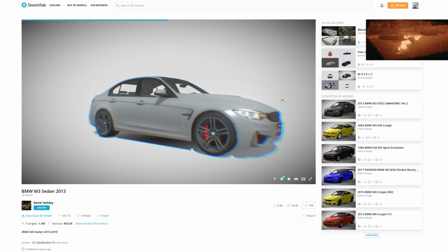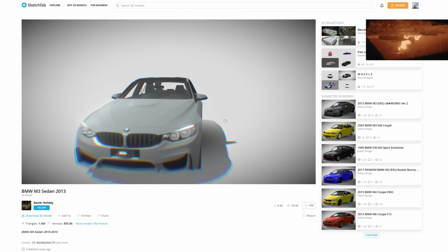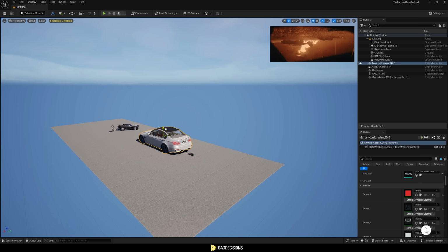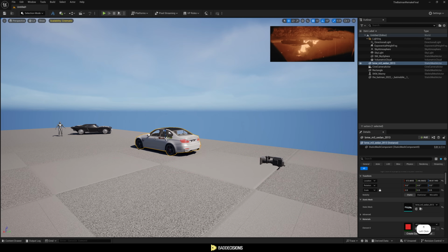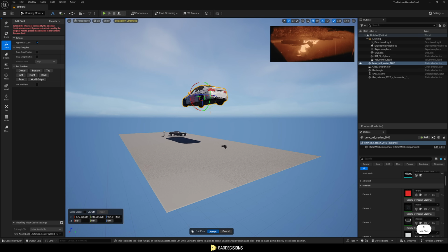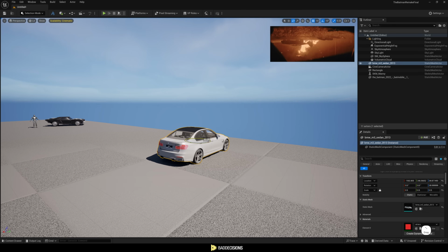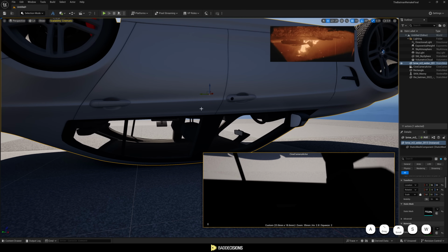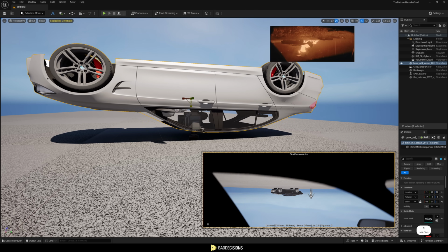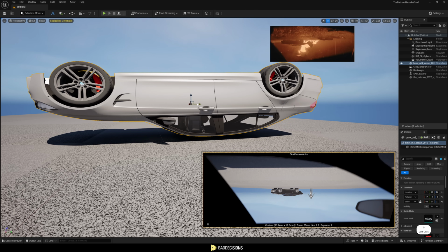So now we need to place the camera inside his vehicle. For that, we are going to use another 3D model from Sketchfab. We will download it as a GLB file, combine static meshes, and import it. We will scale the car down to its correct size and fix its pivot point with a modeling mode, because it was offset by default, which makes transforming the car complicated. Then, we'll flip the car to match the reference and position the camera inside the car. We'll even stretch the car's scale unevenly as needed to fit perfectly in the frame.